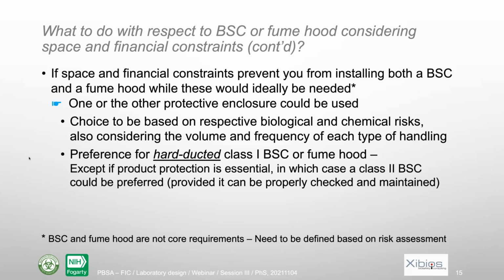If most of the time you work on biological agents and once in a while you need a little bit of toxic chemical, in that case, you should give priority to biological risk and then mostly have a biosafety cabinet. Anyway, if you try to manage both chemical and biological risk in the same protective equipment, in that case, the best options would be a hard ducted, so ducted to the outside, class 1 biosafety cabinet or fume hood.